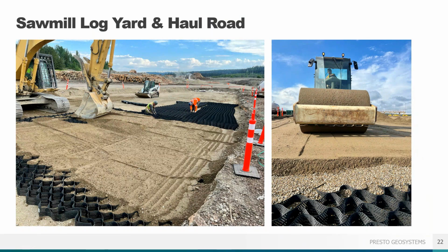Here we see a good technique tip with crews working in parallel. On the far left, the placing of the infill by the excavator, while workers expand and connect new sections of GeoWeb. Far right, we see the roller compaction of the infill. Having a crew with well-defined roles allows this kind of work in parallel and install best practice, and makes for an efficient installation.